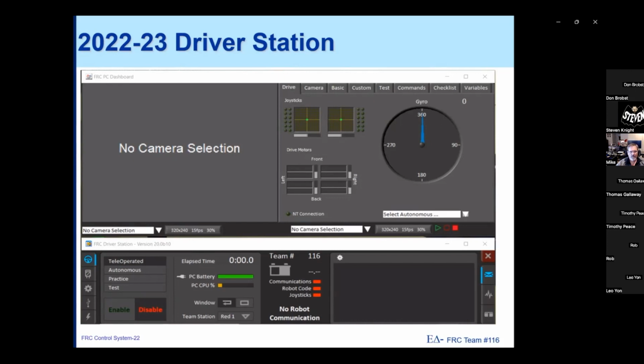It turns out that the ports that are used by the field management system and the robot to talk to the robot drive station, unfortunately, will typically get filtered out by any individual firewall code. So you'll need to turn those off. Just make sure you remember to turn them back on if you're going to plug into the internet, because obviously they're there for security reasons.